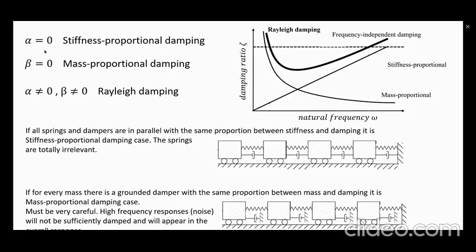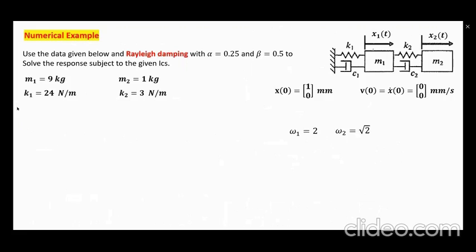That's why just working with mass proportional damping may be convenient, but it's not very good. The same thing, of course, is not true with stiffness proportional damping, because stiffness proportional damping does actually what it's supposed to. Large frequencies are damped a lot, okay? However, it seems that the best case scenario, some experimental results indicate, is to take a combination of the two.